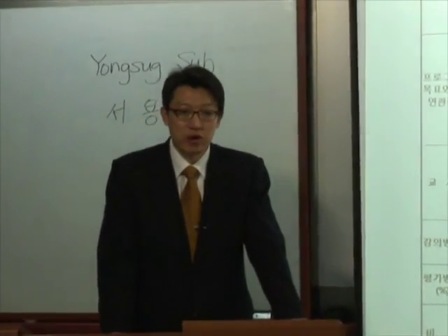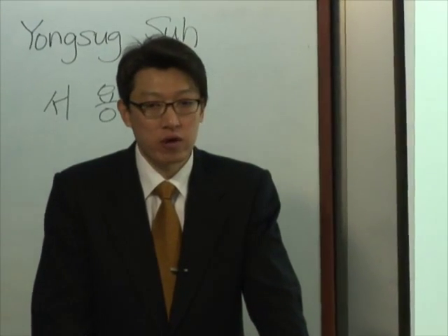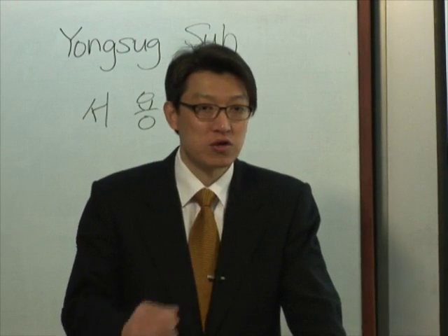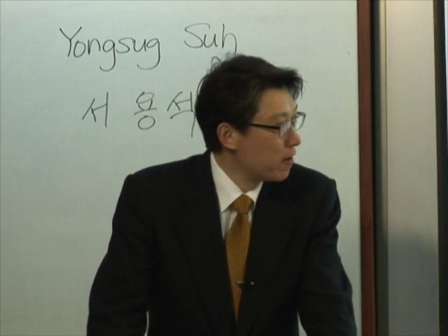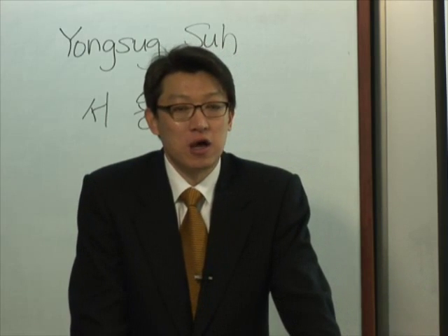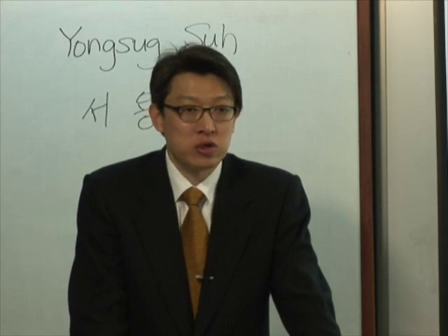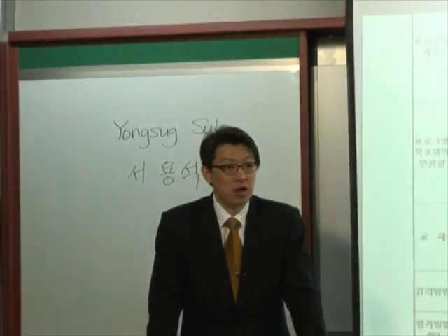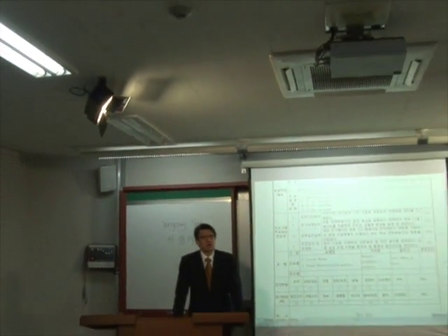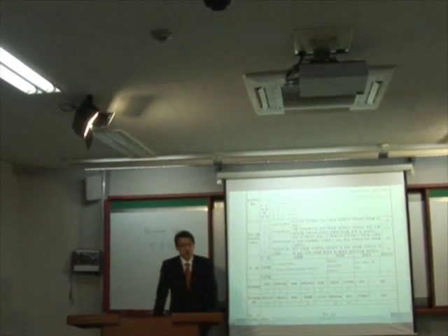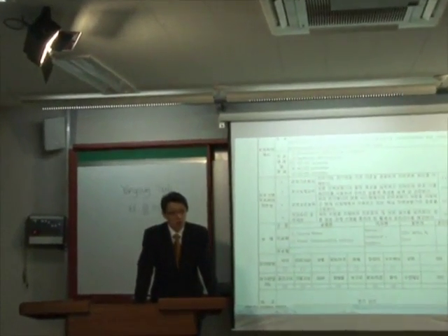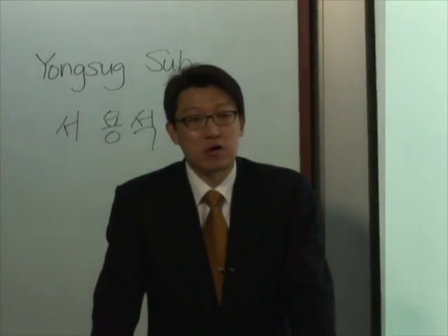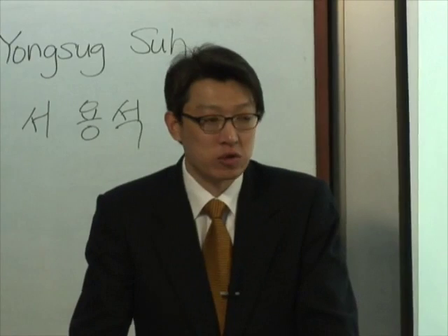Actually, without realizing, power electronics is everywhere around your everyday life. So, for example, this lecture, where is the power electronics? First, light, okay, the light. We have a ballast resonant converters used in this fluorescent light power supply. And what about the projector, okay, the source of the light? We have also a LED, LCD driver or backlight, okay, HID backlight system. That is also part of the resonant converter.